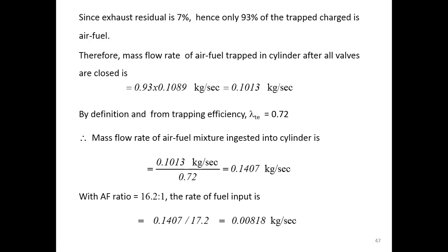Now we use the other information. They said the exhaust residual is 7%. So of the total trapped charge, 100%, 7% is exhaust residual, and only 93% of the trapped charge is the air-fuel mixture.